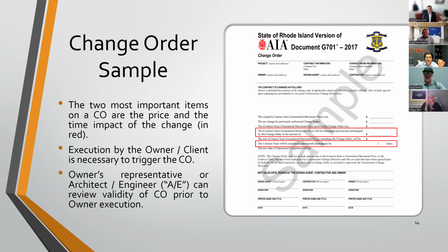And keeping in mind that if you're going to be working on a high rise, the wind speed at ground level could be 10 miles an hour. Nothing too crazy. But when you're several hundred feet up in the air, believe you me, it is much faster than that. So OSHA, I believe, stipulates 25 miles an hour as the max. And let me tell you, from personal experience, it is not fun experiencing anything near that when you're that high up off the ground.